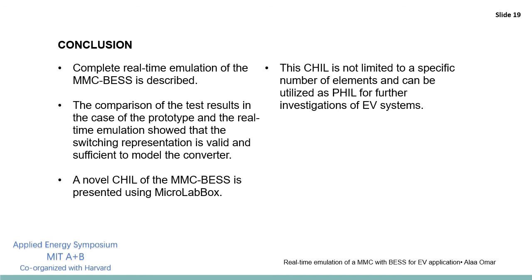This representation of the modular multilevel converter with battery energy storage system is a novel representation of the converter and is implemented on the FPGA of the MicroLabBox from dSPACE. This controller hardware in the loop is not limited to a specific number of elements, and it can be extended and utilized as power hardware in the loop for further investigations of electric vehicle systems.